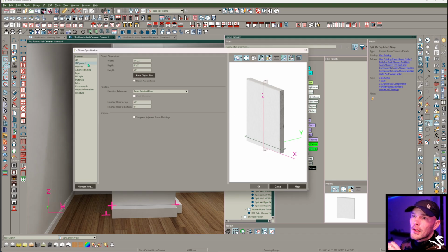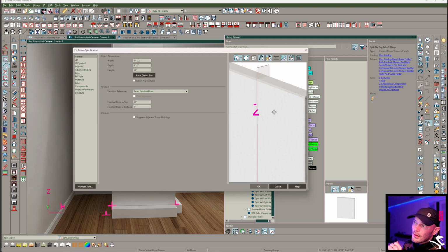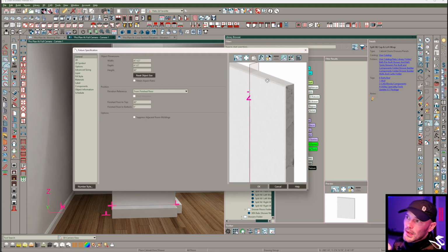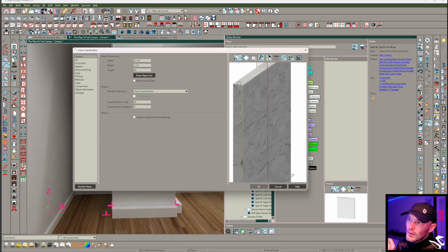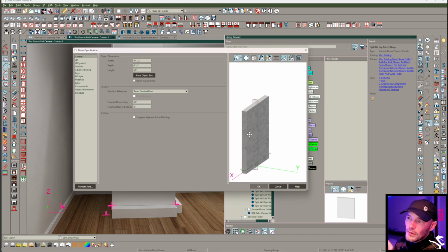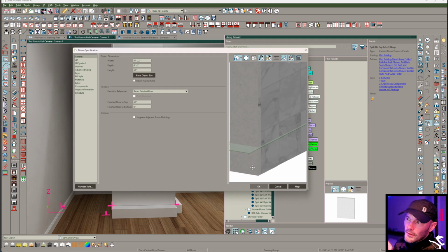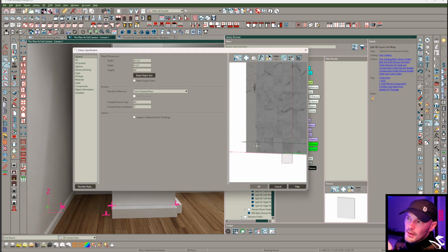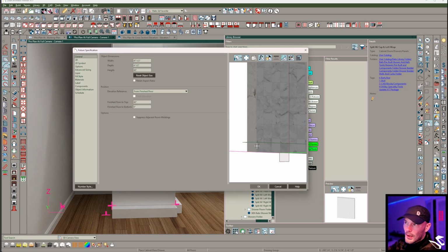Now, what's clever about this? Well, one, the material mapping is a big part of the system. By putting in these little caps and everything, and then setting our stretch zones, that means those caps don't get stretched and they remain there. And that means they can be mapped to different textures, meaning that we can paint the inside of a wall separately from the outside of the wall and have a true full cap wrap on the top and the vertical run. In fact, I believe some of these even stop at 4.5 inches where they might intercede with the curb, so that cap needs to return alongside of that curb.